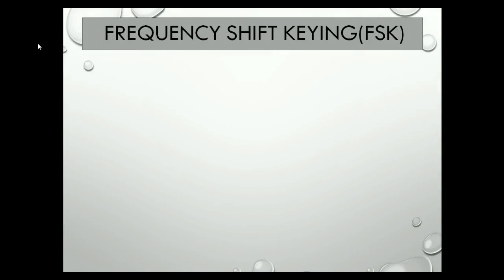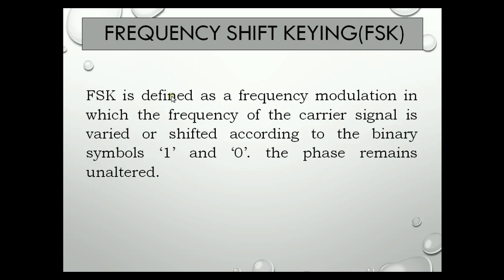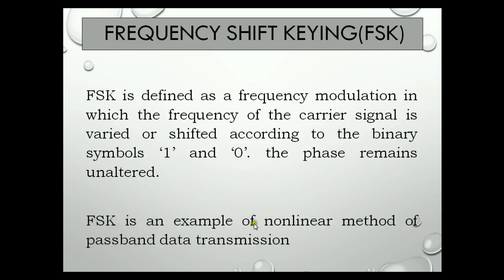The next modulation technique that we are going to discuss is frequency shift keying. FSK is defined as a frequency modulation in which the frequency of the carrier signal is varied or shifted according to the binary symbols 1 and 0. The phase remains unaltered. FSK is an example of a non-linear method of passband data transmission.